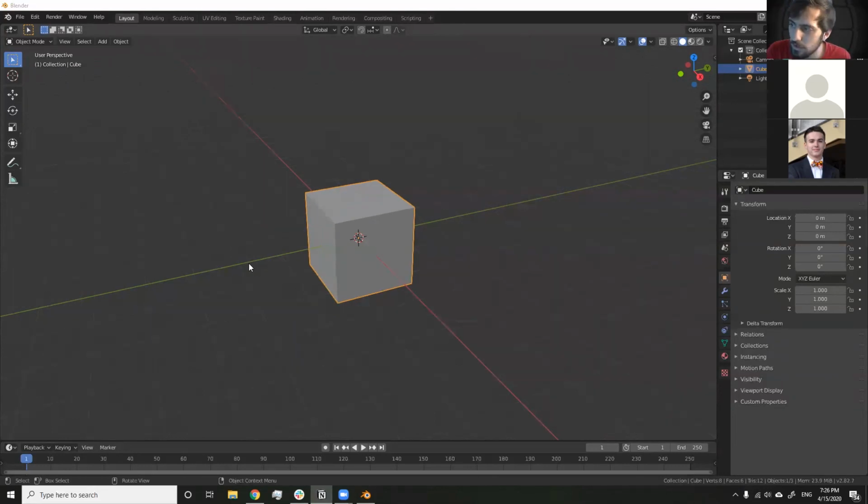The first thing that we want to cover is a couple of the quick shortcuts that you want to keep in mind when you're doing stuff in Blender. So the first one is W, your selection tool. If you continue hitting W, you'll notice that it's going to toggle your selection ability up here between the different selection options. So right now I have select in a circle, so I can kind of paint with it.